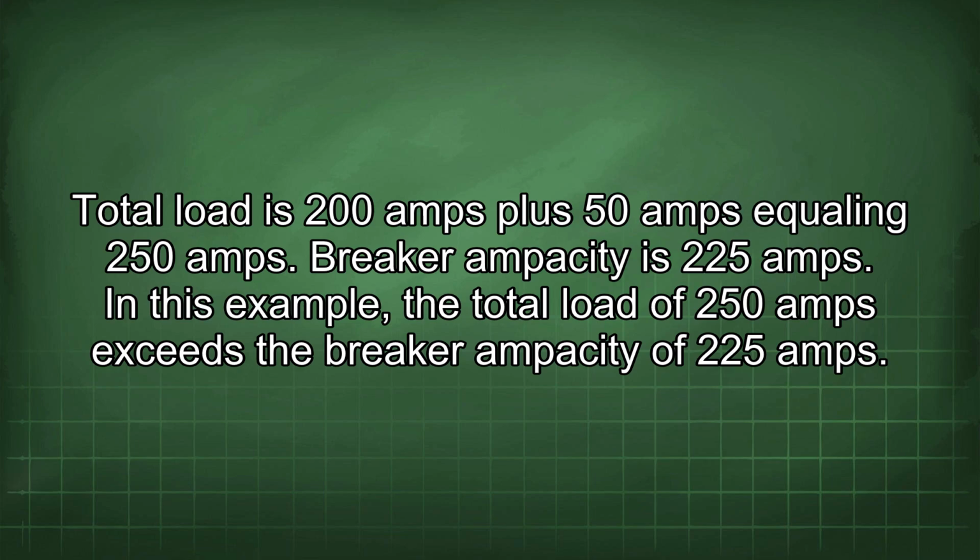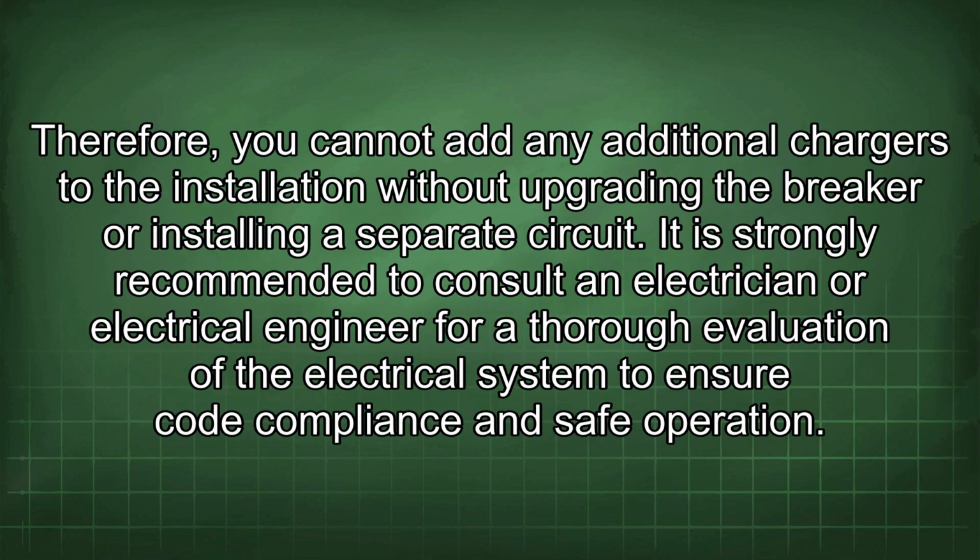In this example, the total load of 250 amps exceeds the breaker ampacity of 225 amps. Therefore, you cannot add any additional chargers to the installation without upgrading the breaker or installing a separate circuit. It is strongly recommended to consult an electrician or electrical engineer for a thorough evaluation of the electrical system to ensure code compliance and safe operation.